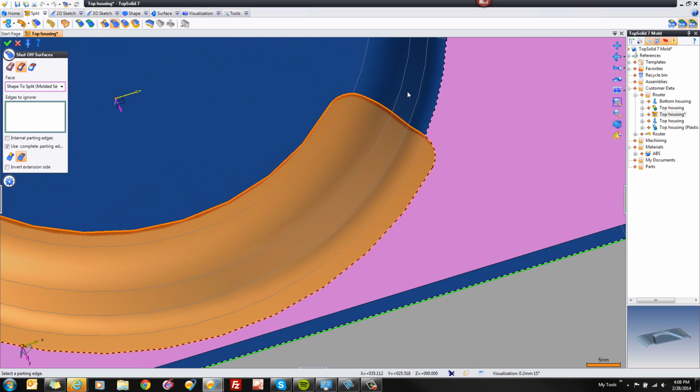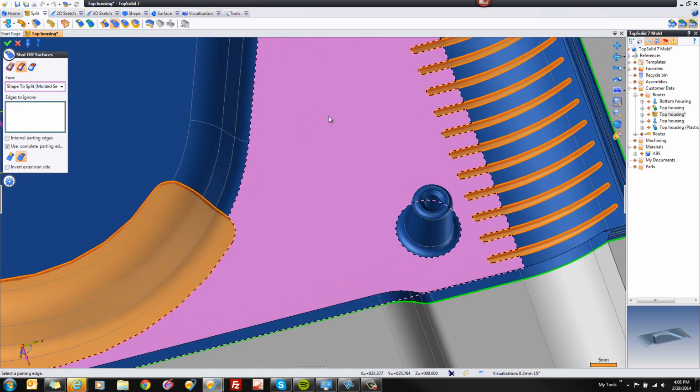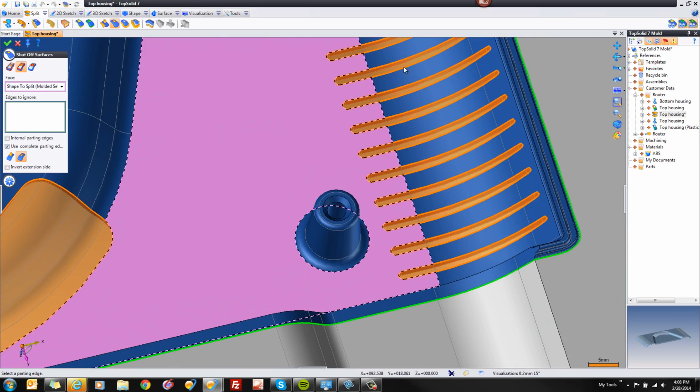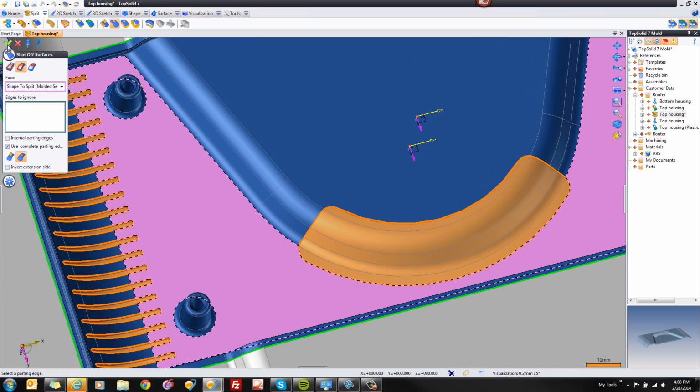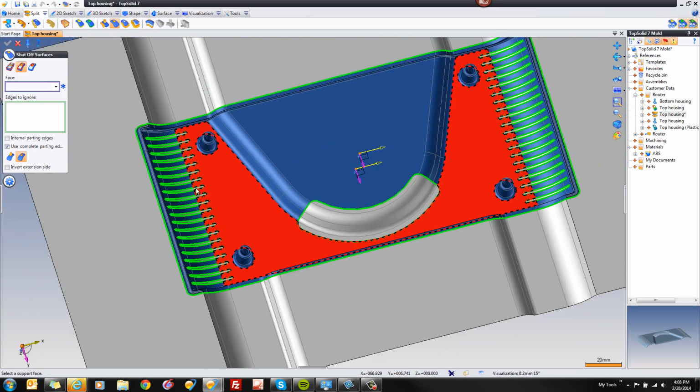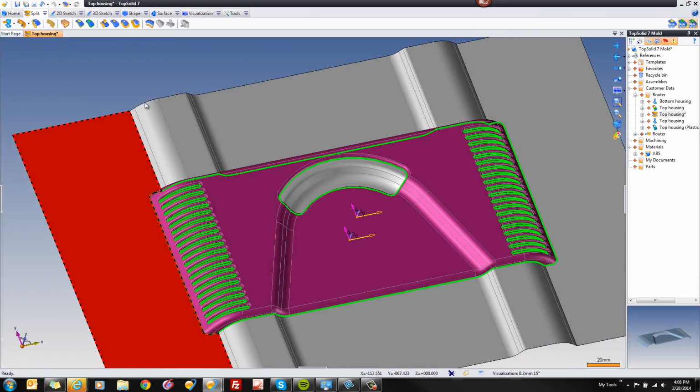And we did this by untrimming all of the surrounding faces automatically for you and retrimming them to the area that you want to use as a shutoff. We did that over there. We did that through all of these shutoffs on the right and the left. Awesome. Let's go ahead and validate. Like this, all of our surfaces are done. Cool. Well, let's take the next step.